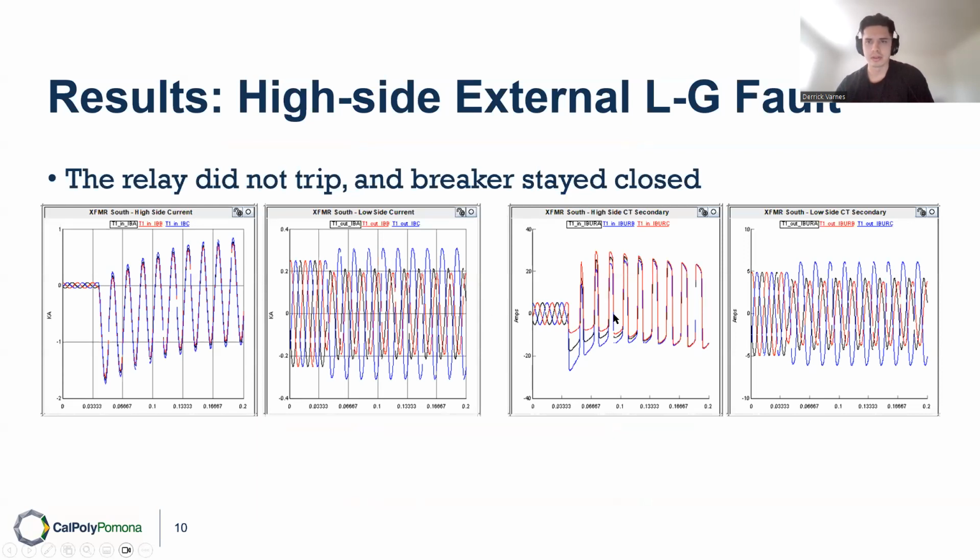These are our current measurements under a fault event. So right before here, these are the normal currents, and then where the fault is applied is where you see these large spikes, especially on the primary side, which is where you expect to see the largest effect.